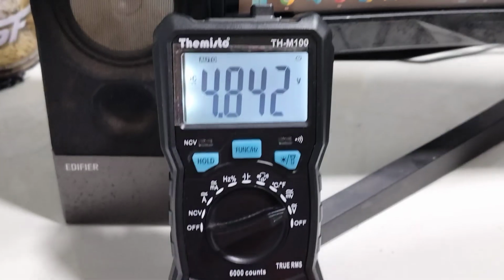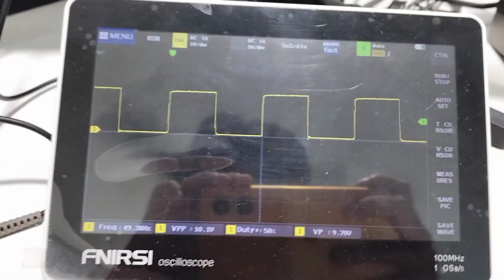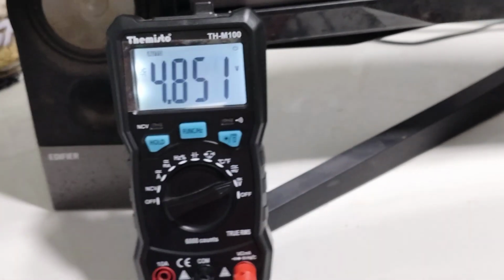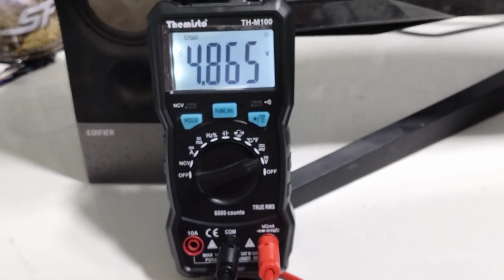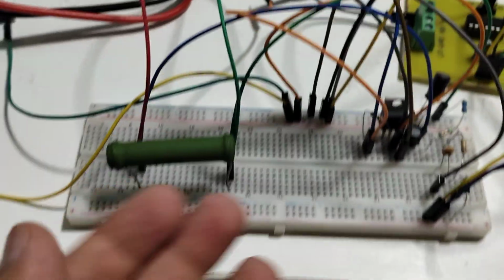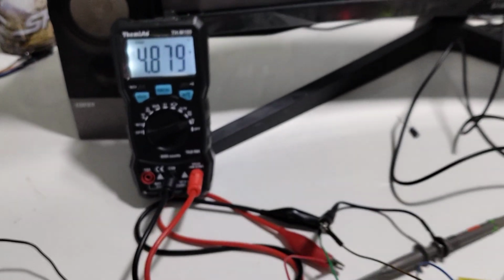And yeah, I connected the power supply here, and you can see we have about 4.84 volts, and it's pushing about exactly 50% duty, which is good. And we're just a little bit off the actual desired 5 volts, just about 100 millivolts, which shouldn't be too much of a worry. And that's probably because of all the breadboard stuff, but other than that, closed loop control seems to be working good. Our gains look fine.